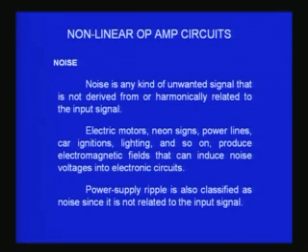All these noise voltages are random, and therefore they can either increase or decrease the input voltage randomly, and if it changes by more than 150 microvolts, the output will change even though my input voltage is not changing, purely because of the noise voltage. The magnitude of the noise voltage is exceeding that 150 microvolt limit, and therefore the output switches automatically without waiting for the input to change. This is an undesirable effect. We do not want that to happen.